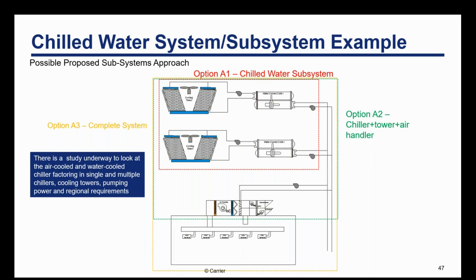So one of the things we can start doing is drawing control diagrams around these components. One of the things we're starting to look at is, do we have a new metric that really looks at the chiller plus the cooling tower plus the pumps? Now you start to factor in, say, hey, do I have high pressure duct piping? I start to look and say, is it better off to put a better chiller in or to put in an oversized cooling tower, considering the cooling tower can also be doing free cooling? So there's a lot of work in the industry and some new metrics being developed, some tools being developed. You may actually see the first of these in the 2022 version of the ASHRAE 90.1. Next slide, please.